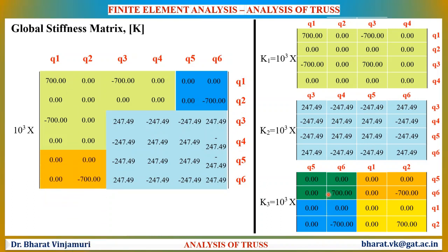Now, the remaining matrix elements, that is the green color one as well as the yellow color one, will correspondingly occupy the other areas of these matrices. These values correspond to the values of Q1, Q2, Q3, Q4, Q5. One needs to be very careful while performing the assembly process. Here this matrix is filled here, therefore obviously the other matrix will be filled in this zone. So once again I repeat, whenever there is overlap, understand that the corresponding elements have to be added.